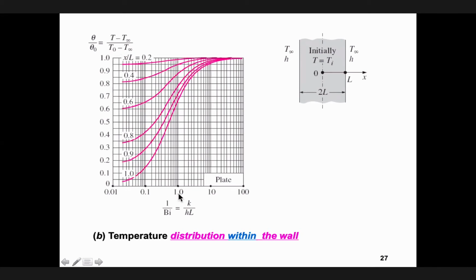it here for, again, the Biot number, and here they give you x over L. L is the half thickness. Again, my friend, please pay attention. x is measured from the center, and x is at any point that you would like from the center to the surface. x here is 0. Therefore, x equal L means at the surface. This represents the temperature at the surface. Any question? If I'm going fast, let me know, please.